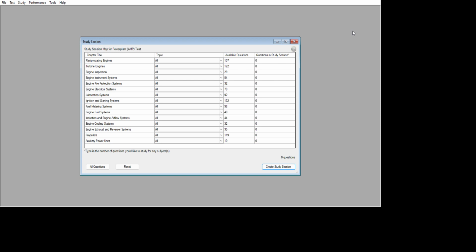When the centrifugal force acting on the propeller governor flyweights overcomes the tension on the speeder spring, the propeller is in what speed condition? Overspeed.